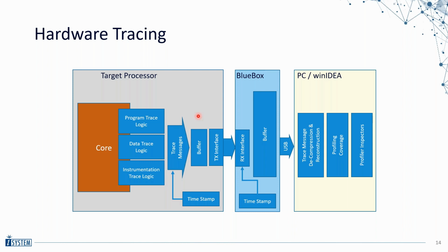That emulation adapter has a microcontroller that emulates the microcontroller that was previously on your PCB, but it also makes the serial trace interface like Nexus available. That would be a way to get trace data while still having the same behavior of the application as before, even if you don't have the serial trace interface available on your PCB.